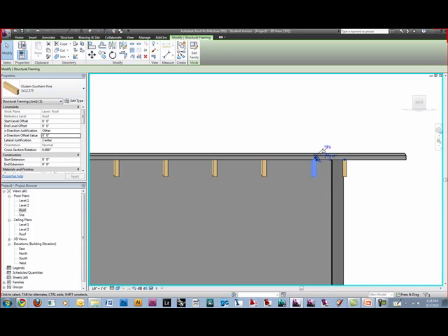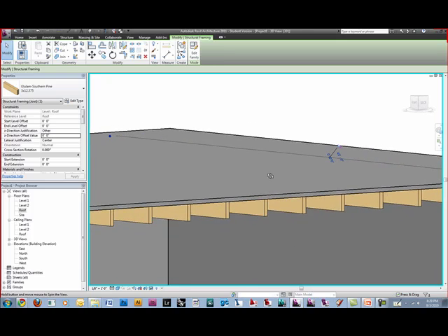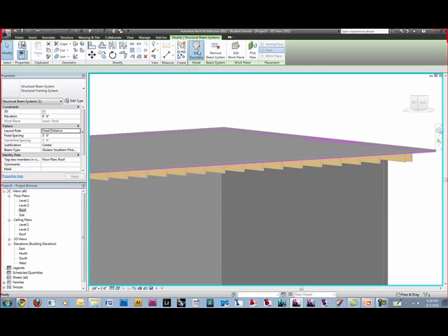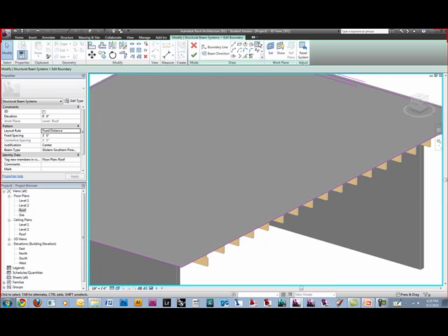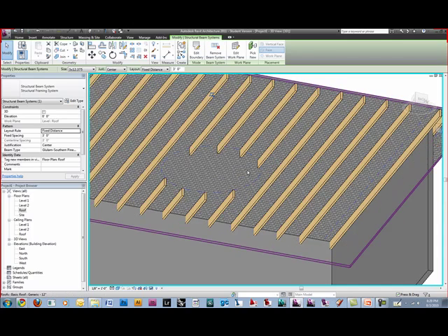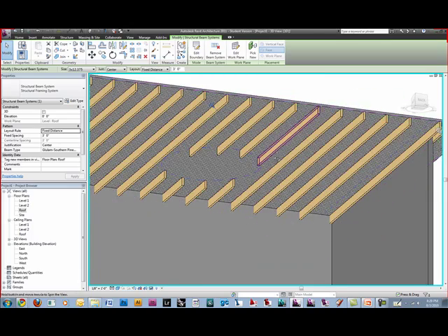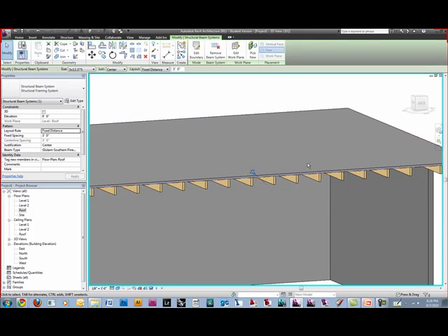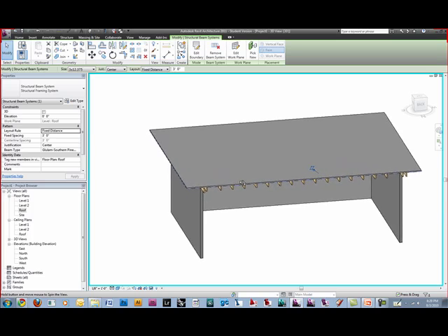Alright, it's really easy to move this stuff around once you actually know what's going on. There's a basic beam system, and it has that same profile shape that your floors do. So if I edit this boundary and cut out a circle in the middle of it, it'll cut out a circle of beams as well. If I place that there and say finish sketch, now when I look at it, it'll have a circle cut out. So it works the same way as a floor, except now it's a series of beams. I'm not going to do that because it doesn't make any sense, but if you wanted to. It does make sense if you're trying to take the whole building down, if you're trying to cut out, yeah, no structure going there.